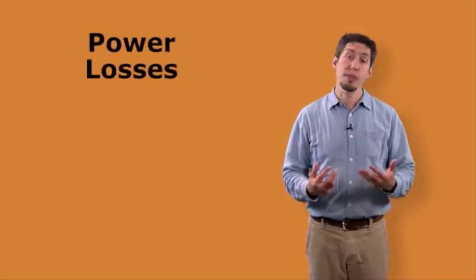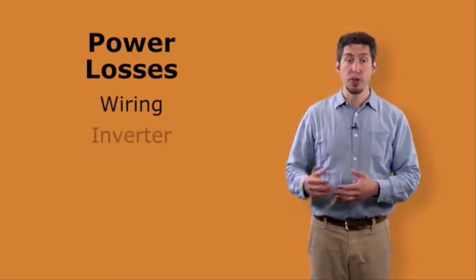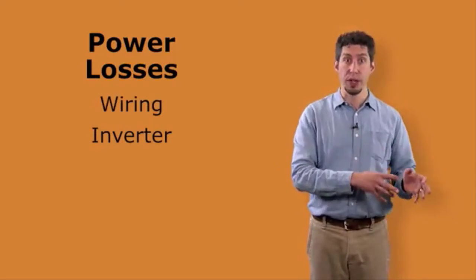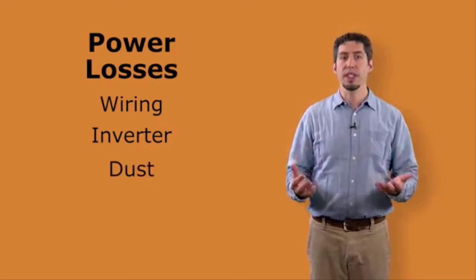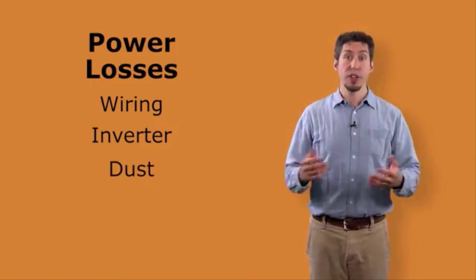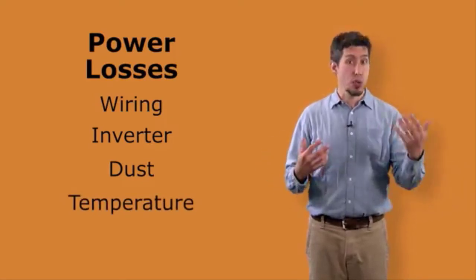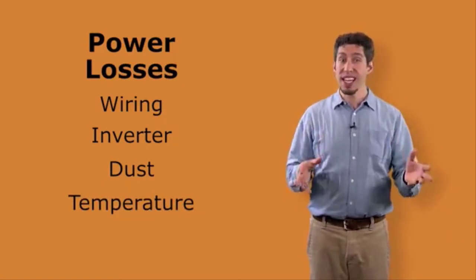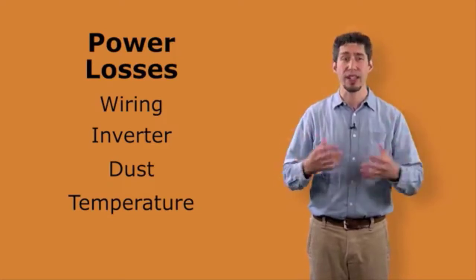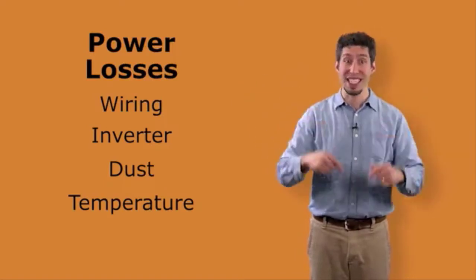Aside from that internal efficiency of the solar panel, there are losses from things such as wiring mismatches from junctions and differences in wire sizing, the inverter, which converts the direct current to alternating current, as well as simple things like dust that falls on the panel's surface, which lowers the amount of sunlight available to be converted. Another efficiency limitation is temperature mismatch. Panels are rated under test conditions, 25 degrees Celsius, about 77 degrees Fahrenheit. In reality, when it's sunny outside, the actual temperature is usually much higher. What's interesting about photovoltaic panels is that when the temperature goes up, the efficiency goes down.